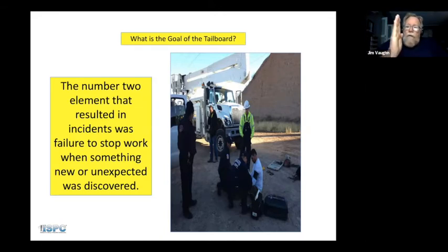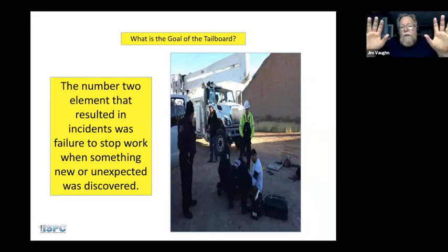We are a vertical industry, and what OSHA recognizes is that the quality of our training and our awareness of the hazards in the environment is what keeps us safe. That's the reason why we can move up to within just 18 inches of an energized conductor where everybody else has to stay 10 feet back.